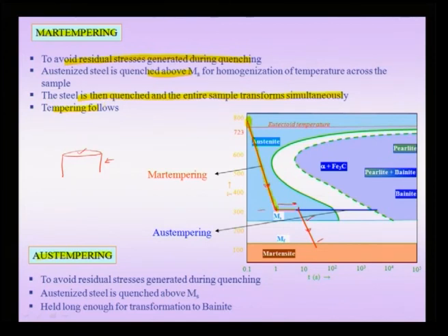So, there is a slight variation in the quenching process, and this heat treatment cycle now involves a quench regime. Say for instance, I can label this XY. So, I start from the X point, quench it to Y point, then I go to Z, and then quench it to room temperature. So, therefore, during the XY I am cooling it to avoid the nose of the TTT diagram, then I hold it above the Ms temperature, so that still we are in the gamma phase field, but we are not allowing any transformation.